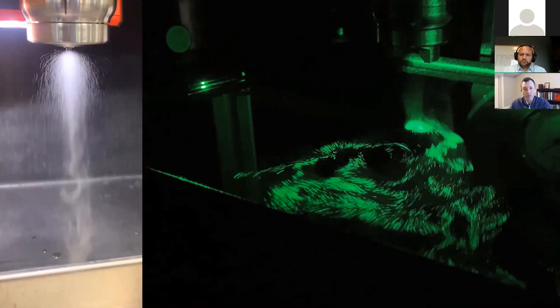So the way we would approach this is, first and foremost, what is your transfer efficiency, right? Do you see a lot of spray going elsewhere, or do we have a reasonable expectation that the fluid that's leaving the nozzle is reaching the target and staying there? That's the first place to stand. And to assess that, at least in a trial case, you could spray into a target that could then be weighed. Given the flow rate, given the amount of time sprayed, how much material actually stayed with the target, or a surrogate target that would hold the material that you could take to the side and weigh. So assessing transfer efficiency is very important.